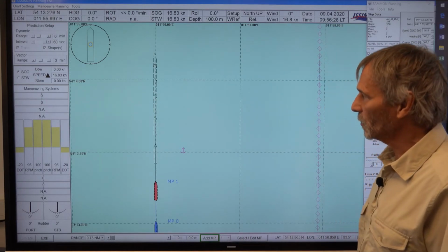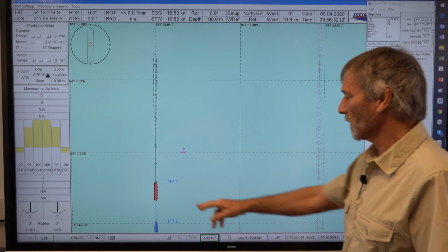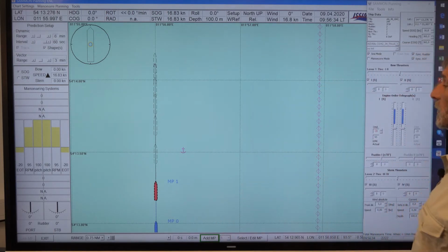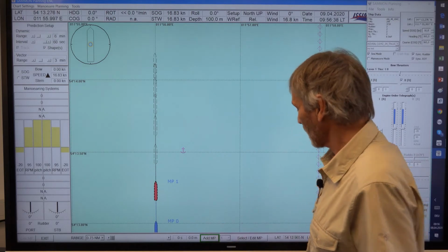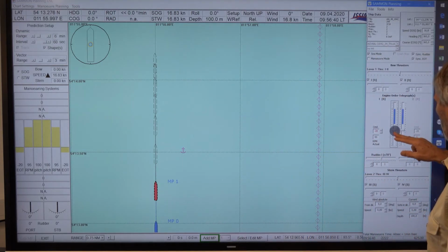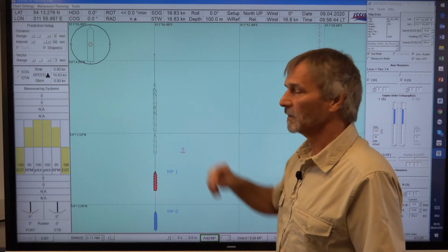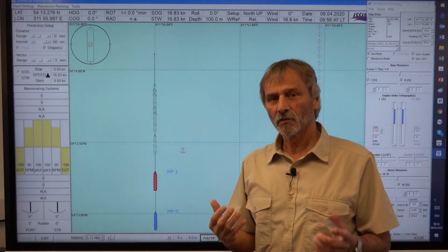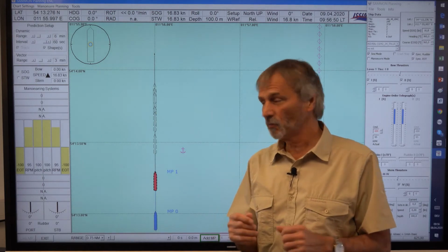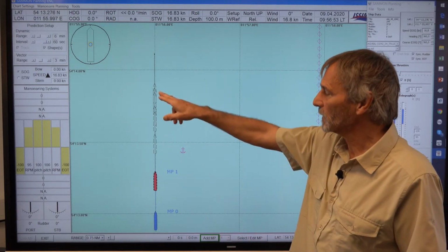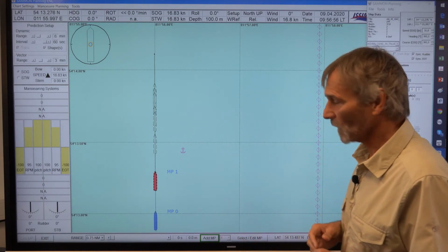And the question, so this is the initial position, it's 16.8 knots at this position. And this is our stopping distance with full astern. So we can see it here. But the question is, could we shorten our stopping distance? Could we achieve a smaller stopping distance than these 1,100 meters? Yes, we can.